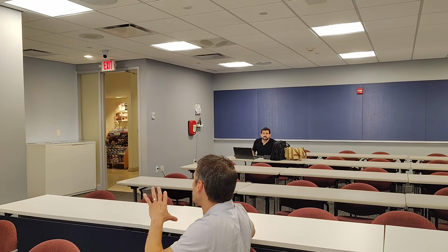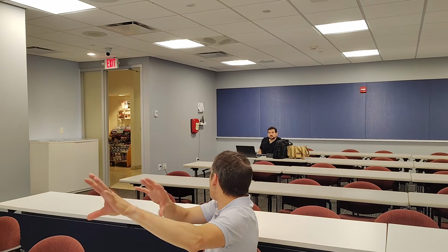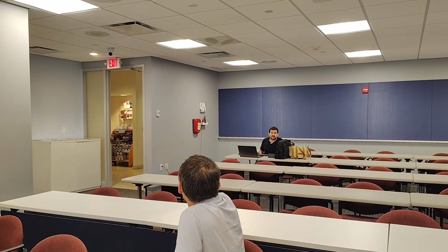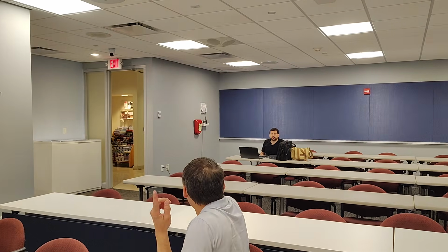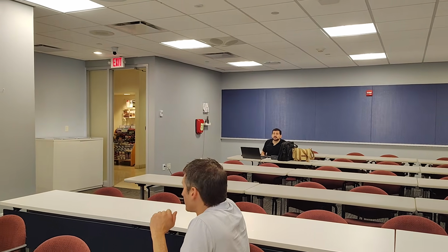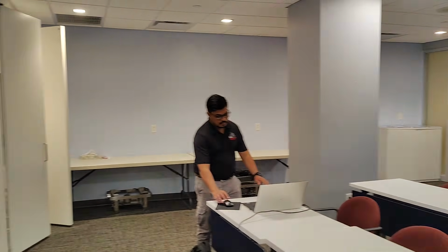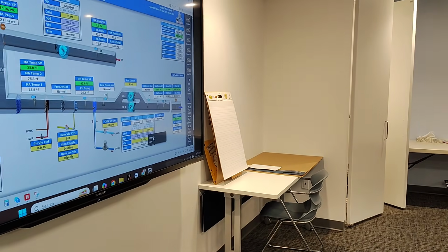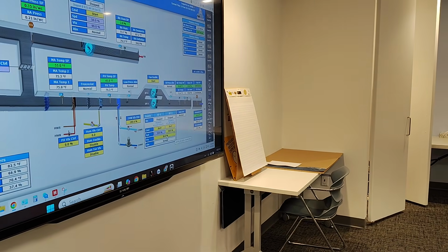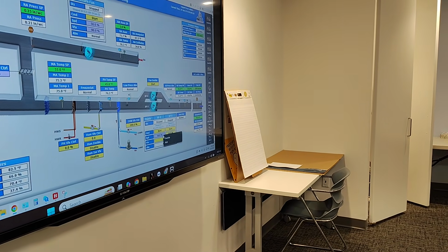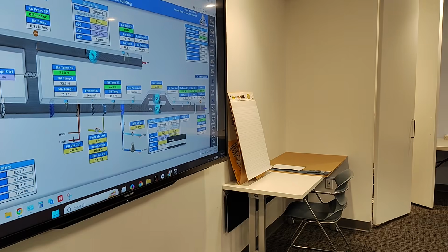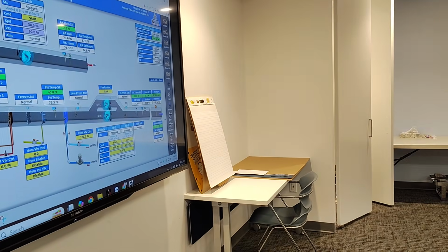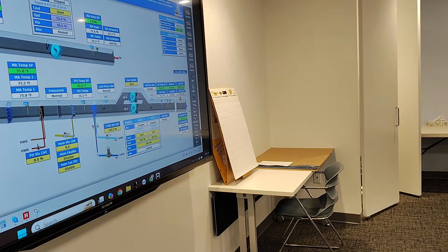But with the integrated system, we could make adjustments here to the fan. You can manually adjust the fan speed, you can adjust the static pressure set point. Yeah, right here. Dinesh, change the fan speed. No, but manually, can we relinquish it so it can be automatic? Yes, make it automatic. Now, what it does in automatic, we can't control. Right? So now, because you change the static pressure set point, we don't know what they're programmed. Make the static pressure set point 2 inches.